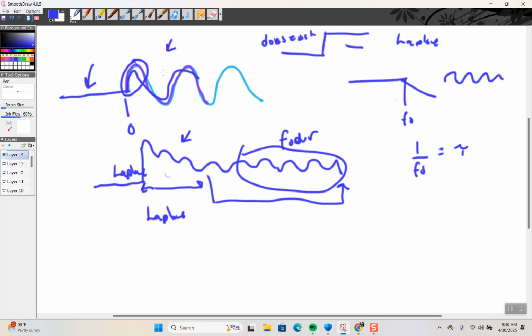And you can set an oscilloscope to just record in time, so record a millisecond and then stop. Let's say you have a reset, then you would be able to see it turn off and on. But if this sine wave is a kilohertz and the cutoff frequency is relatively high, it happens so fast you won't see it.